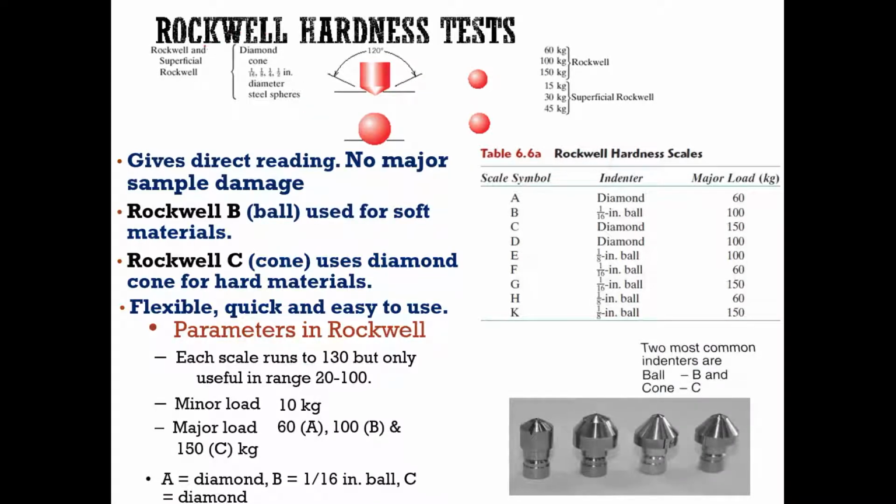We call it Rockwell Hardness Testing. Okay, what is the difference between Rockwell and other hardness testing? Let us see here. This Rockwell hardness testing uses two types of indenter, which is conical shape and also sphere shape. The material for the conical shape will be diamond, and steel will be the material for the sphere indenter. So they do not use any pyramid shape. The difference between pyramid and conical is the angle here. It's around 120 degrees.